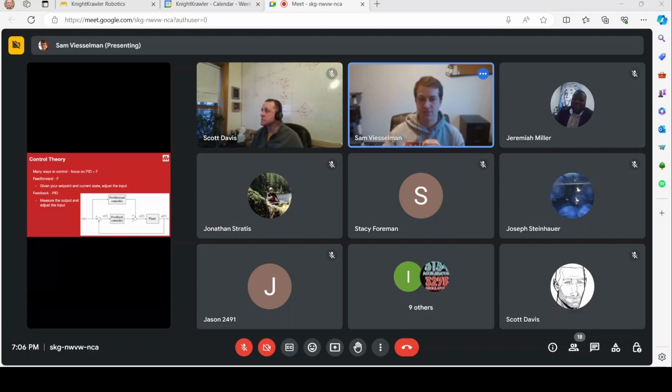I wanted to highlight this feed forward term here, usually called F, and you'll see F or kF if you've dove into the code on this. All feed forward is saying is, given I want my mechanism to do something, I know I have to give it at least this much voltage or duty cycle.